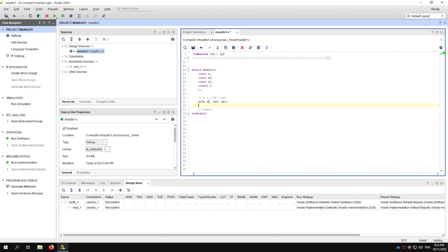What we said is we were going to define not S. I actually don't like this name S1. It's not clear that it's inverted S. So I'm going to terminate with an underscore, which is an allowed character. I'm going to call my inverted S signal S underscore. Again, underscore is an allowed character inside the name of my wire.